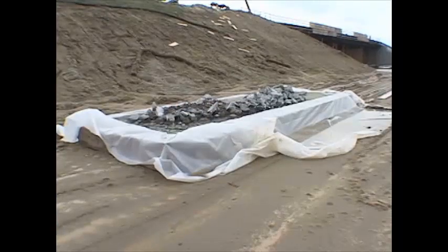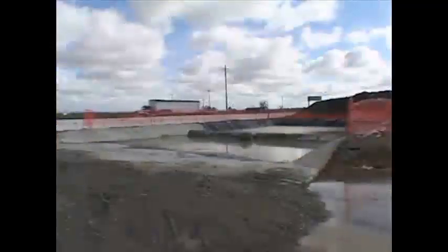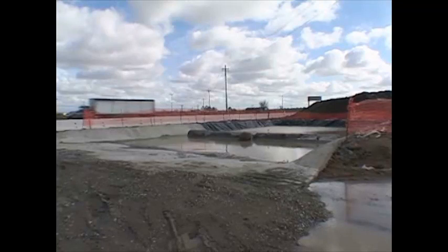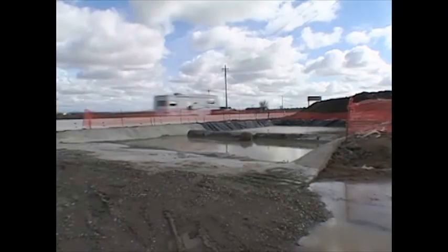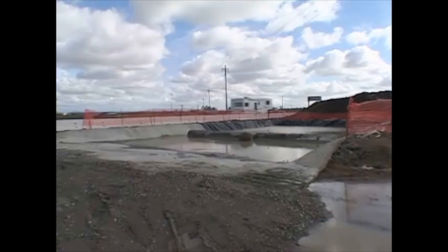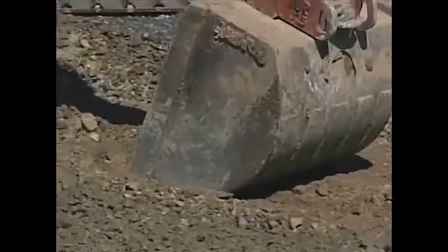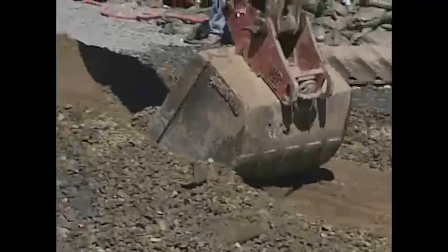Once concrete washout facilities are no longer needed, the hardened concrete must be broken up, removed, and disposed of properly. Dispose of Portland cement concrete, dried residue, slurries, or liquid waste in conformance with project special provisions. Materials used to construct temporary concrete washout facilities become the property of the contractor, and it is the contractor's responsibility to remove and dispose of these materials properly. Holes, depressions, or other ground disturbance must be backfilled and repaired.